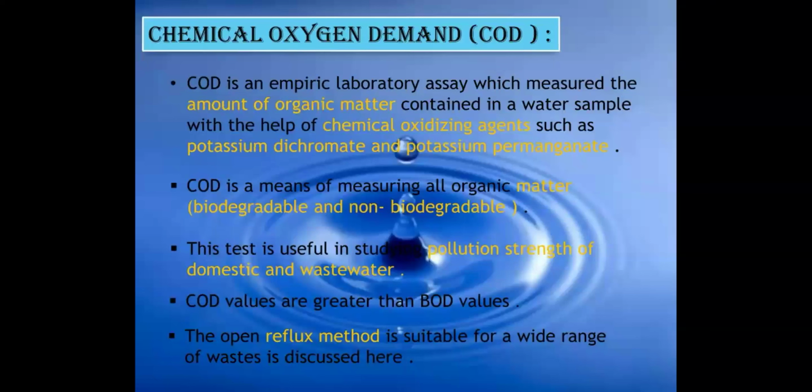This is the chemical oxygen demand. COD is an empirical laboratory assay which measures the amount of organic matter contained in a water sample with the help of chemical oxidizing agents such as potassium dichromate and potassium permanganate. COD is a means of measuring all organic matter, biodegradable and non-biodegradable.